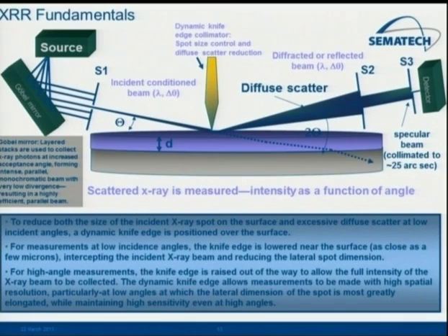You bounce the X-rays off the surface. They, of course, penetrate deeper into the substrate, particularly if it's a reflective film in the optical. And then you measure the scattering and you measure the reflectance of the spot. Not shown on here, you can also measure some other properties. You can measure the diffraction, which gives you some idea of the crystallinity, and you can measure things like fluorescence, because as the X-rays hit certain atoms in the substrate, they emit photons at different energies, and you can detect those and start to get more information about the properties of the film.